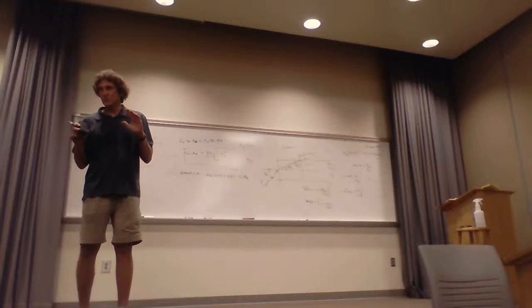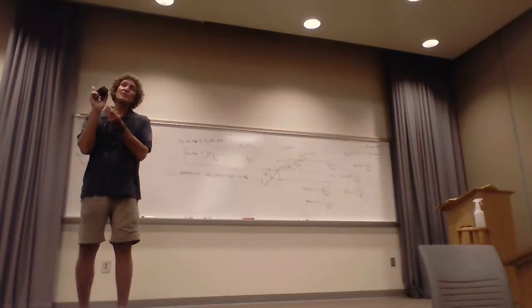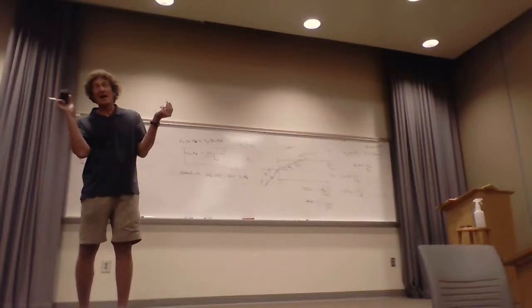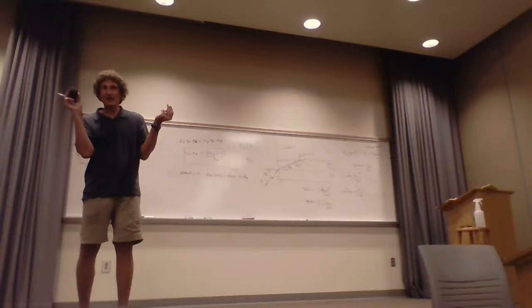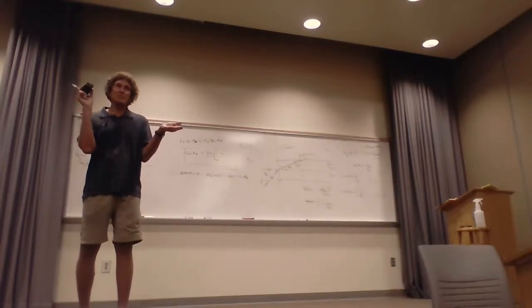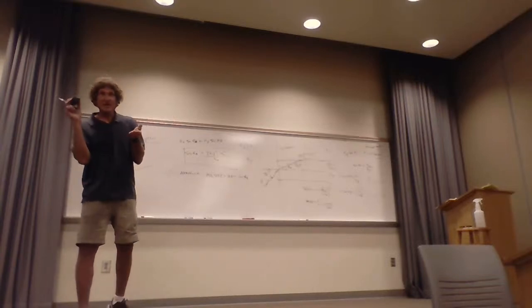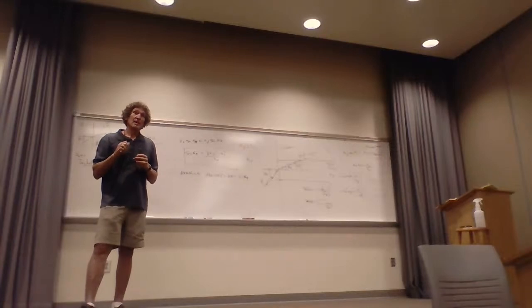Those are used for multi-mode fiber, and I don't want to spend time on it, but it's fiber optic stuff where you've got two different frequencies of light propagating down. You're going to ask me, why do you need that? I don't know exactly. Usually it's because you're trying to get two communication channels down one, and you're probably going on the cheaper fiber instead of running both cables. Have you dealt with graded index fiber? Dealt with multi-mode. Now, I don't know which one's more expensive. I think graded index, huh? Single mode's a lot more expensive.